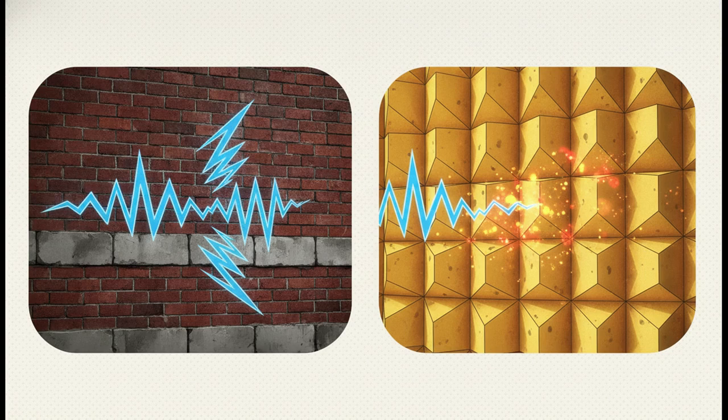On the other side, we have noise absorbers. Instead of acting like a wall, these act like a sponge. They use highly porous materials such as acoustical tiles, open-cell rubber foams, or melamine sponges to capture sound waves and literally convert that acoustic energy into microscopic heat inside the material itself. A truly well-engineered room is going to utilize a strategic mix of both.